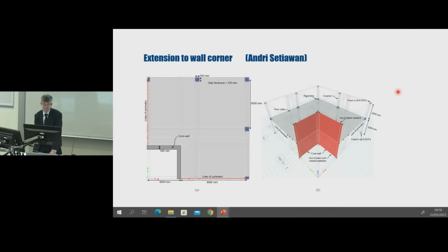Having developed this refined joint shell punching model, we made use of it to examine the problem of punching shear at the corner of shear walls in multi-story buildings. So this picture is showing on plan a quarter of the floor plate. And then this is the central core, similar to the one we saw at the beginning of the lecture, which is there to resist lateral loads.